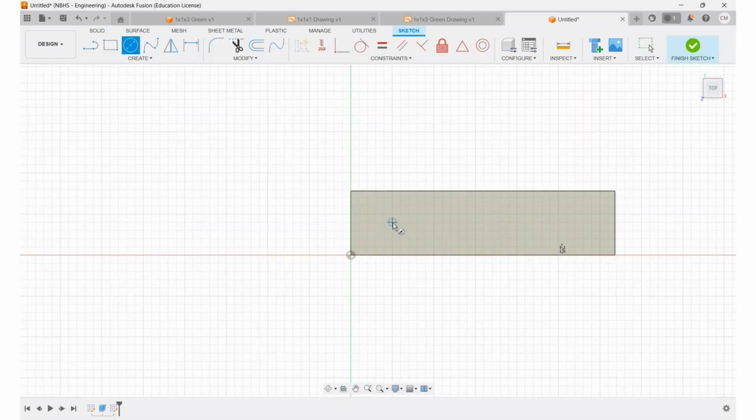And what I will do is lay out a stud. Again, I'm not particular about where I place it. I just want to make sure that I'm not hitting any lines, points, anything like that that will add relationships I don't want or need and would make it more difficult. So this diameter is going to be 4.8 millimeters. Again, that's just kind of a Lego standard, so we're going to keep using it.